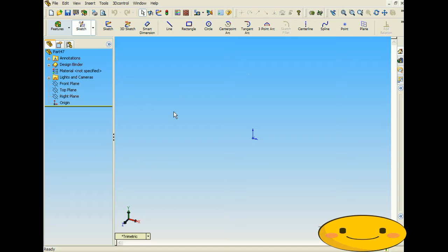In this tutorial, I'm going to show you how to insert a sketch plane while you're inside of a sketch. The reason you'd want to do this is if you have one sketch that you're making, say a 3D sketch, and you've already made a certain part of it, and you want a certain plane and positioning. You're able to add another sketch plane that you'll sketch along in that sketch without going out of it, creating a new plane, and creating a brand new sketch. So you'll have everything in one sketch rather than in two sketches.